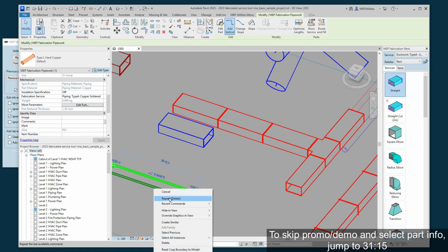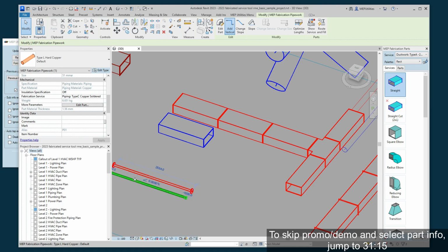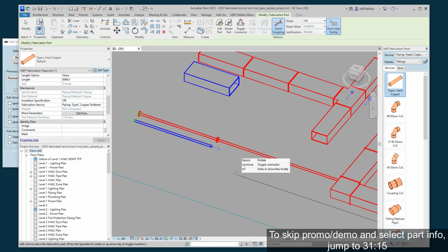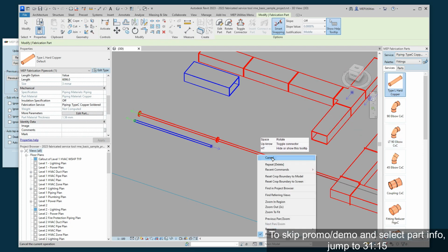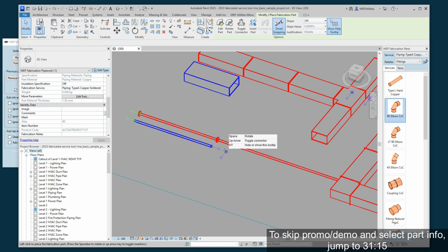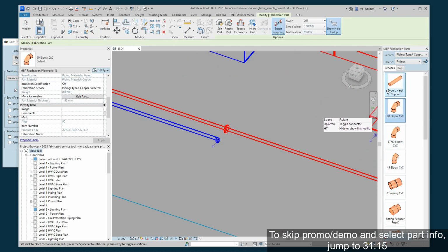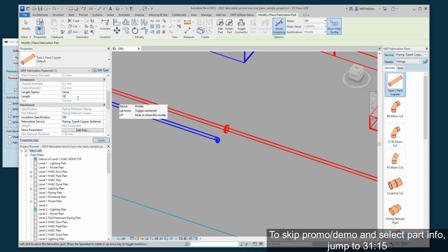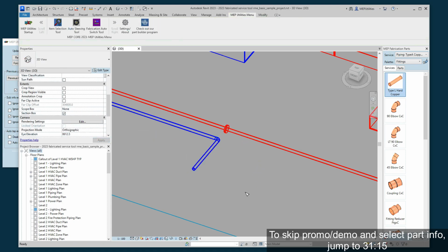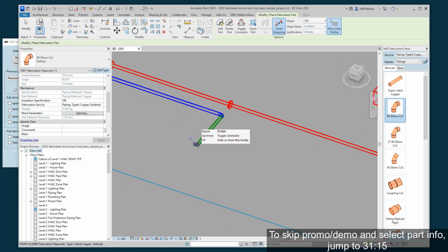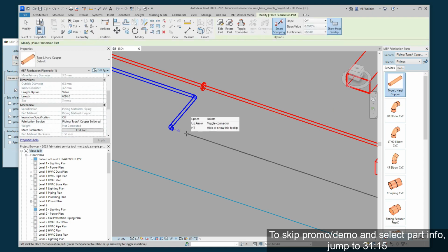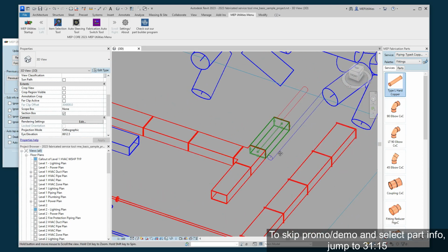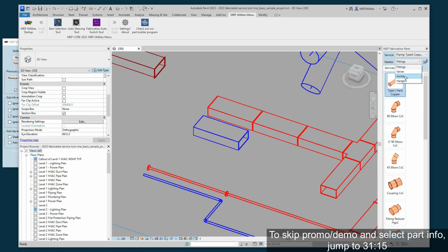And then you can use, let me grab this service. Alright, and then we'll place this pipe. And we'll grab the other service. And we'll do a 90-degree here. And then we'll go forward, and we'll go however much we want to go, I don't know, 1,000. And we'll turn right. And we'll continue straight. There you go. Like, you can quickly throw out parts and start getting them assigned without any issues. Quickly build stuff.